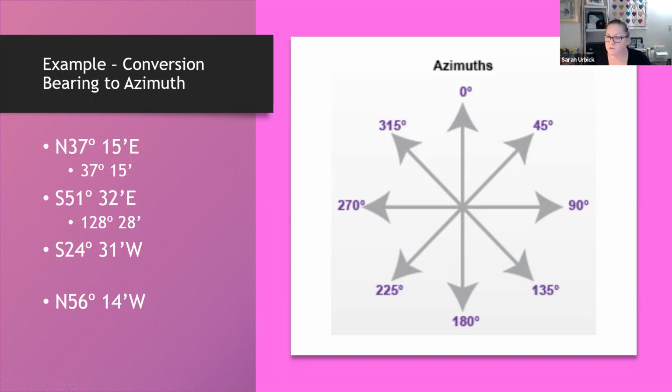Othello, do you want to tell us what you did? Maybe we can help you get on the right path. What I ended up doing was I subtracted 180 by the 51.32. And that is correct, but it's the minutes that are probably throwing off the number. Oh, right. Yeah, I messed up on my calculation that way. Thank you. All right, cool. That's why I seriously recommend get rid of the minutes, convert it into a decimal of degrees.